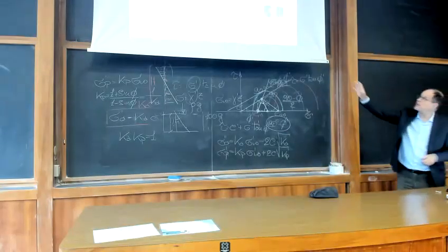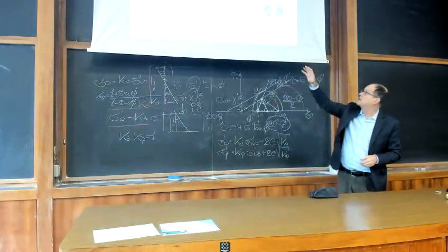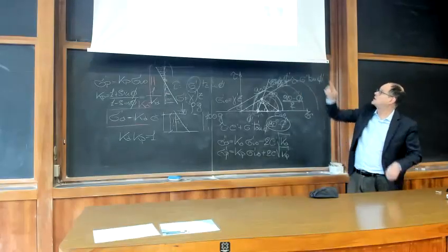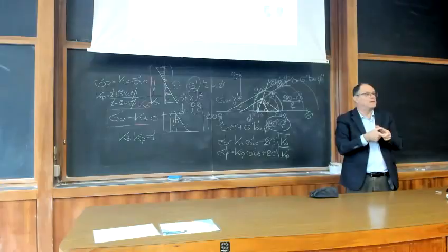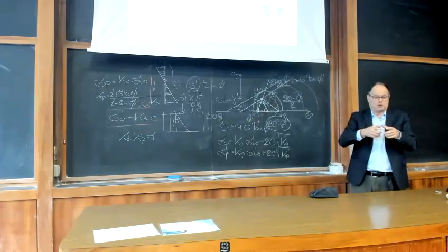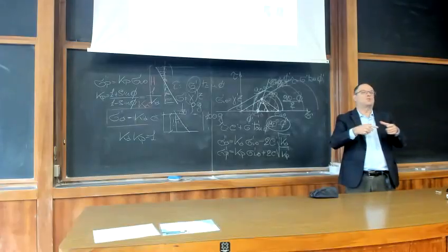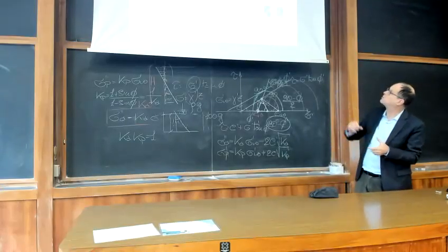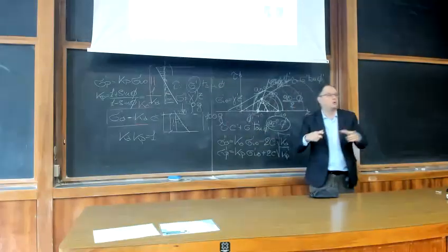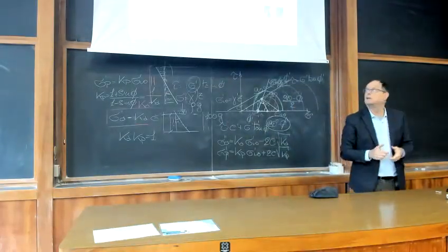So what you get here is exactly what you would get under a real foundation. In this case, this was a very small foundation, only 5 centimeters diameter, but corresponding to about 2.5 meters. I think these tests were run under 50g, so you have to multiply all dimensions by 50.